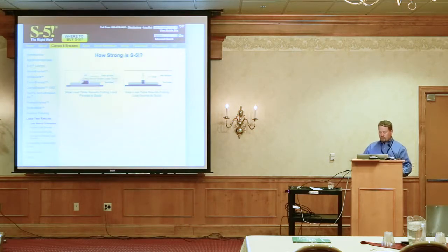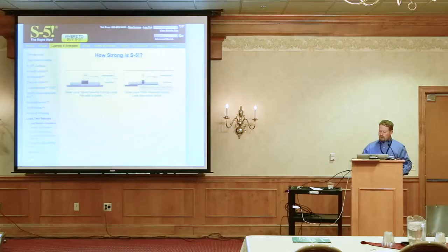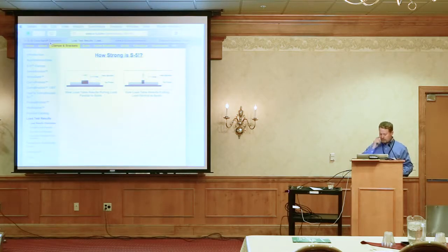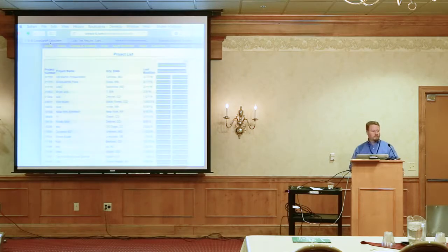In this diagram, you can see where we're showing the load with the arrow. So when we're testing, we're pulling parallel to the seam for the holding strength. When you get into pulling load normal, you can see we're pulling in an upward direction. So normal load is an engineering term that just means perpendicular to the surface of the panel.